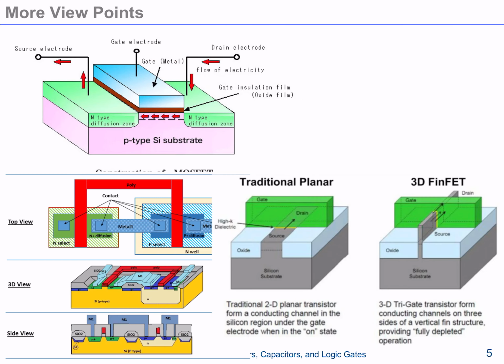So newer devices tend to try to wrap around the gate. One of the big new developments in the chip industry is this gate that wraps around this thin layer of silicon shown in gray over here. We call that 3D, like having fins, so they're called FinFET.